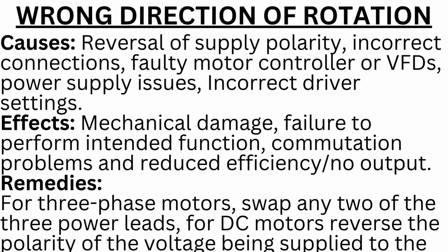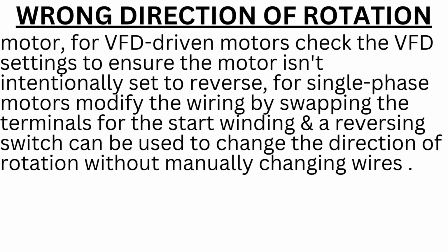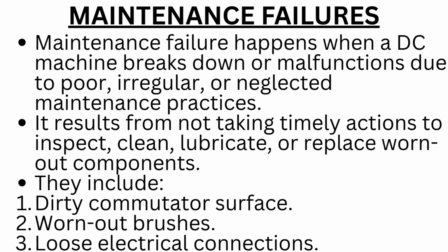For DC motors, reverse the polarity of the voltage being supplied to the motor. For VFD-driven motors, check the VFD settings to ensure the motor isn't intentionally set to reverse. For single-phase motors, modify the wiring by swapping the terminals for the start winding, and a reversing switch can be used to change the direction of rotation without manually changing wires. Now let us look at maintenance failures.